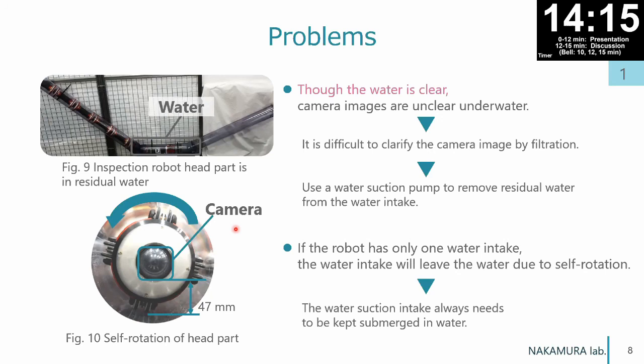If you were using ultrasound, it would be advantageous to have water in the pipe, wouldn't it? Because then you would have a couplant to couple your ultrasound to the pipe wall. You could look for cracks that are maybe even hidden.